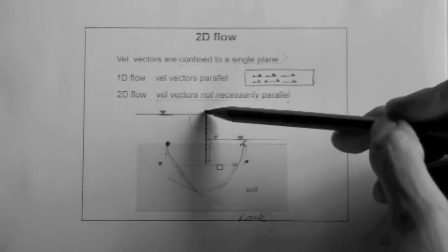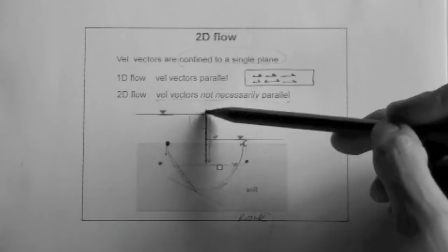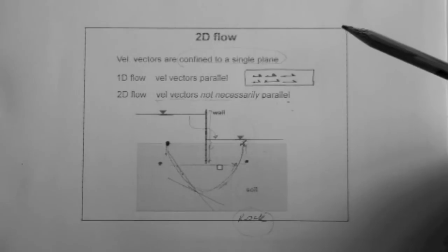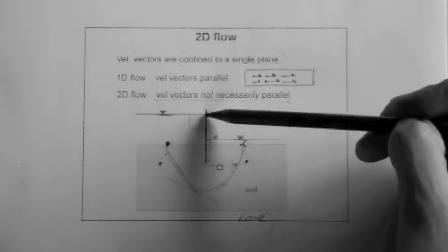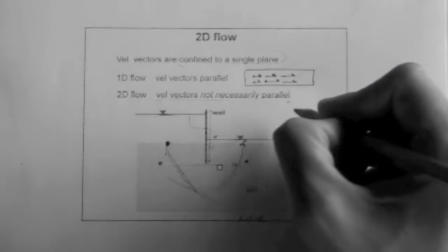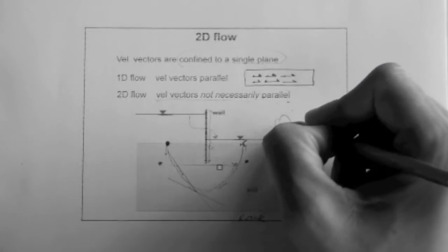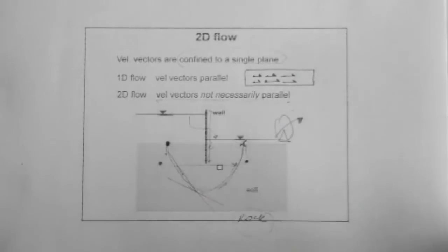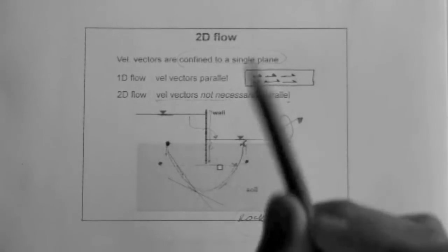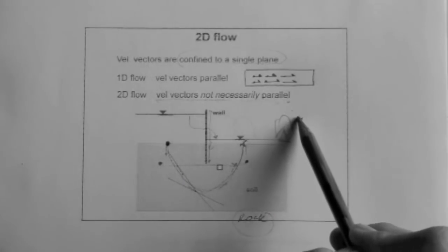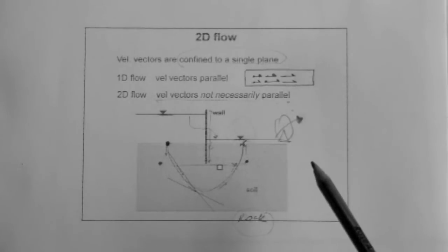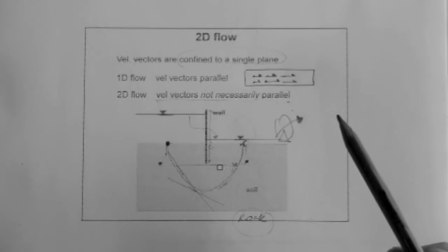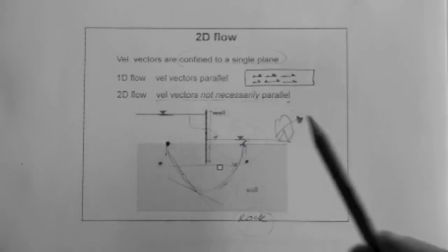So what we do is we place a wall. In this case we actually insert a wall that is already prefabricated. We can talk about that later on when we take the foundations course. But essentially what we do is place a wall and then we place a pump to remove the water from this location so that we can bring a crew in here and work, or equipment. Now, as you can imagine, the type of pump that you are going to design or select for this operation depends on how much water comes in here per unit time. That is, what is the flow rate expected at this location?